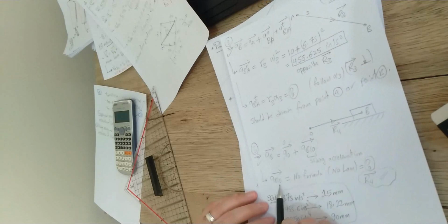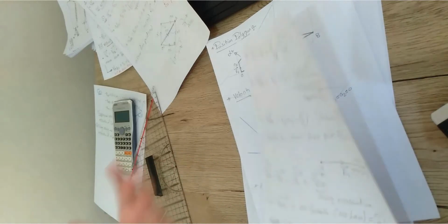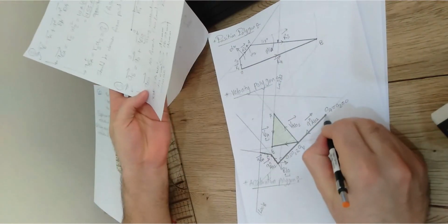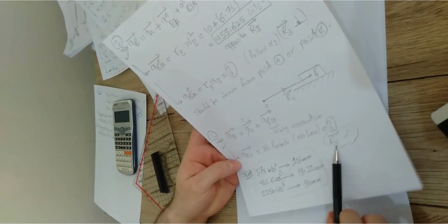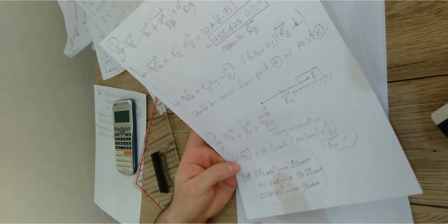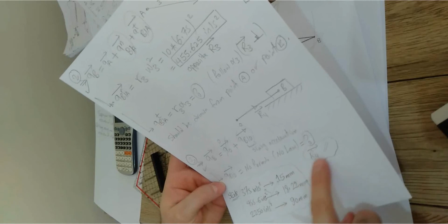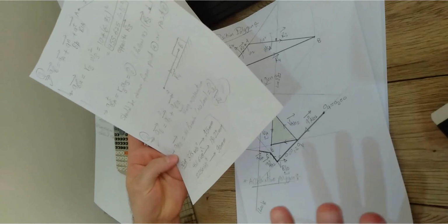It has B relative to O2, so relative to O, so it would be drawn from either point B or point O. The point that we already have here, we don't have point B yet, but we have point O, which should be this point. So starting from this point, you're gonna draw a line that is parallel to the R4. Parallel here doesn't mean opposite or the same direction. We have no clue because this acceleration is not given. So we're just gonna draw a line that is parallel to the R4. The end of this line should give us point B, which we have no clue where it is yet.